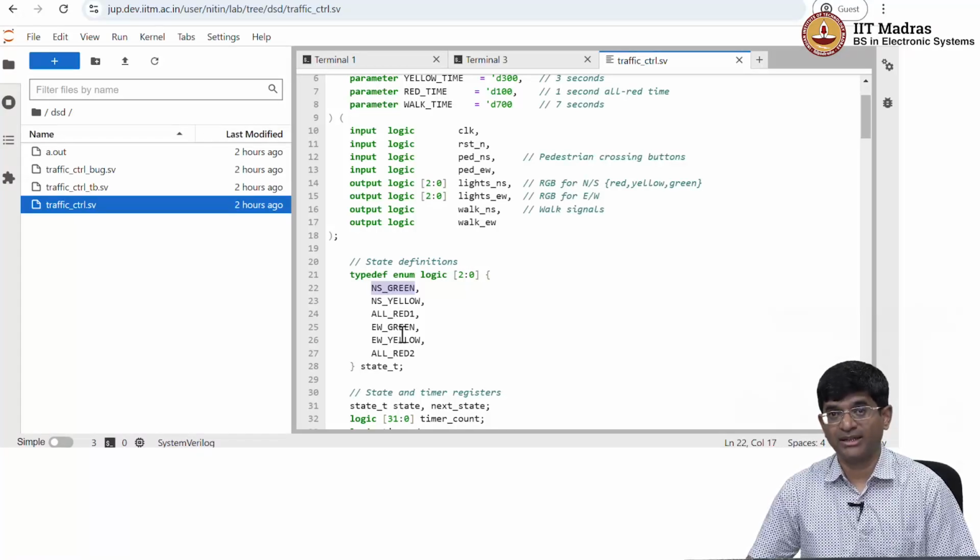Now, keep in mind that as far as simulation is concerned, none of that happens. In simulation, it just keeps it as 000, 001 and so on. It does not do the state assignment optimization and so on unless we actually go for synthesis of the resulting circuit.